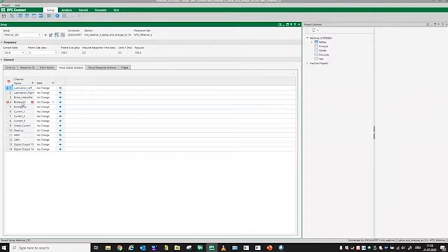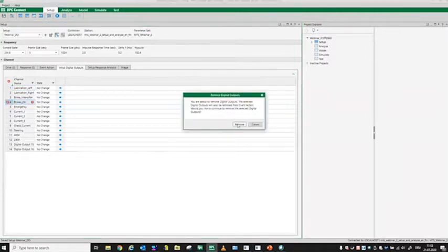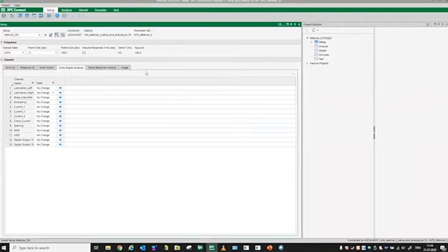So what you can just easily do is say, okay, I'm just going to remove the brakes. Say, okay, remove, it will accomplish and tell you that all the actions connected to the brake will be removed. So only the digital output for the brakes will be removed in all your available actions. And then that's it. I can directly work with the setup, reconnect, and run the station.